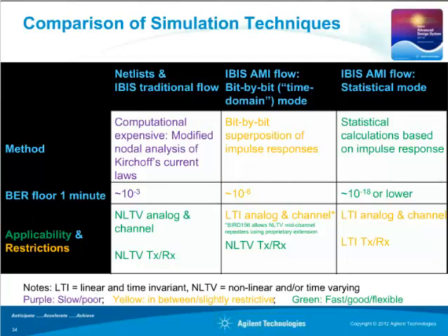IBIS AMI breaks down into 2. So channel simulation has 2 modes. One is superposition of bits. This is a time domain technique. It allows you to be very flexible in terms of the transmitter and receiver, but places the constraint on the channel that it's linear time invariant. And that's actually a reasonable constraint when you think about the kinds of channels that you're working with, on the electrical side anyway. Let's focus that on electrical.